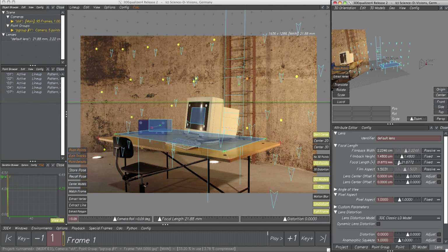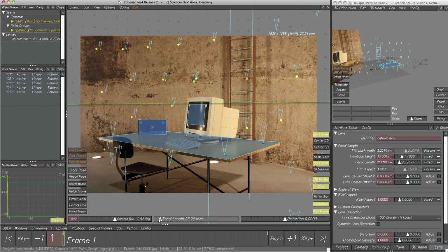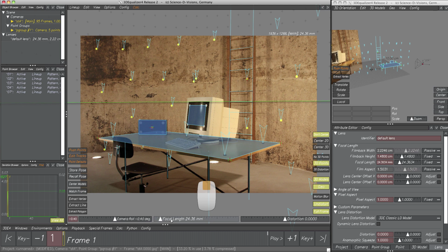For a good alignment, we will continue adjusting with the focal length slider with the lineup controls. Every time focal length or distortion are modified, the deviation will be roughly calculated, indicating if the set values suit for the shot or not. This helps fine-tuning an alignment, since very wrong values of course can be seen with the naked eye. For a more precise adjustment, just click right or left beside the knob with the middle mouse button, depending in which direction you want to adjust the value.